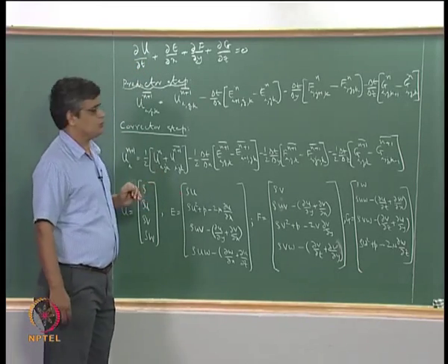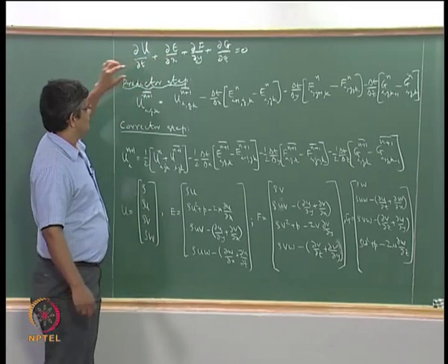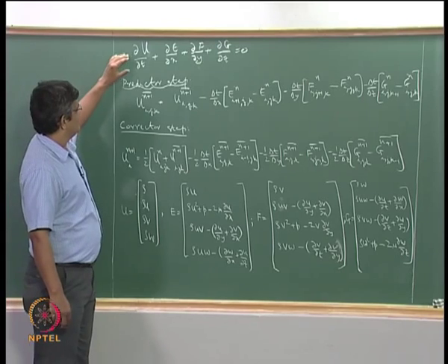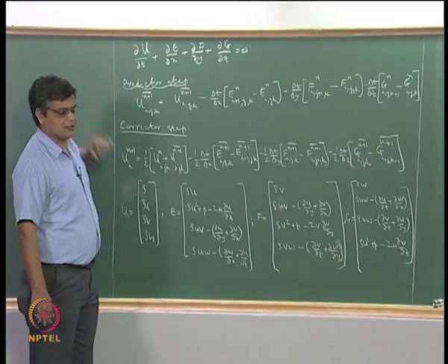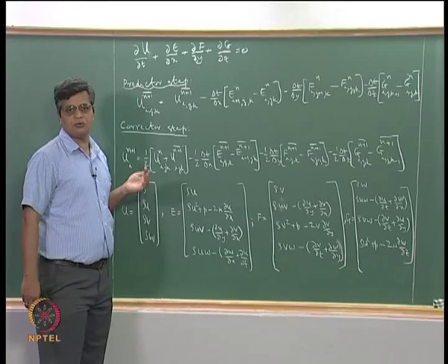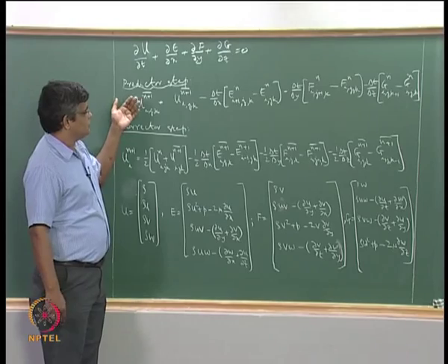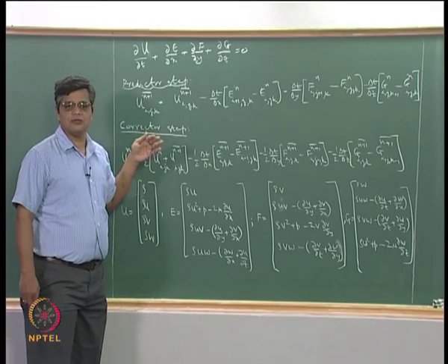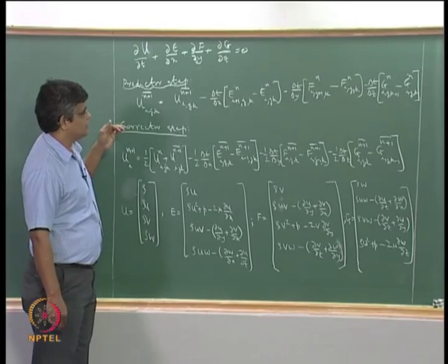We will come to those 4 terms, and once you have an equation like this, we can look at how U, which is the variable of interest, evolves with time by going through a 2-step process to go from n to n plus 1 in the MacCormack explicit method.